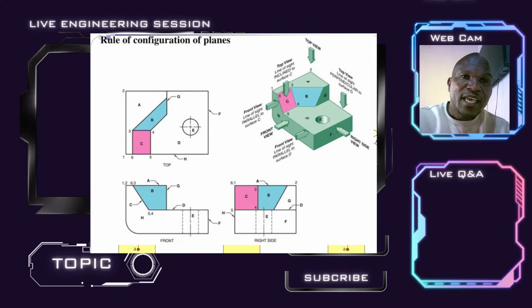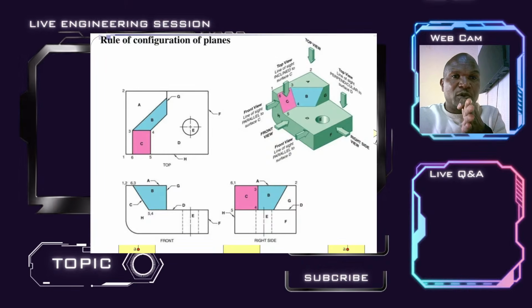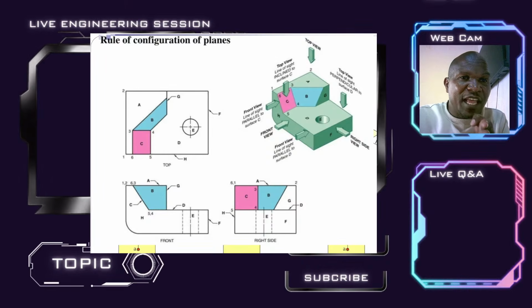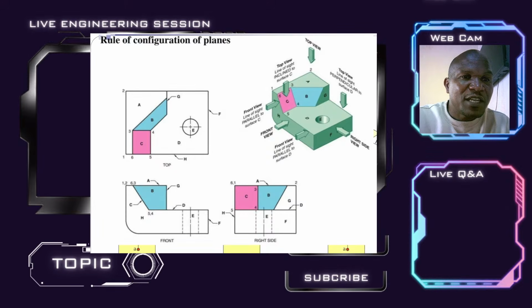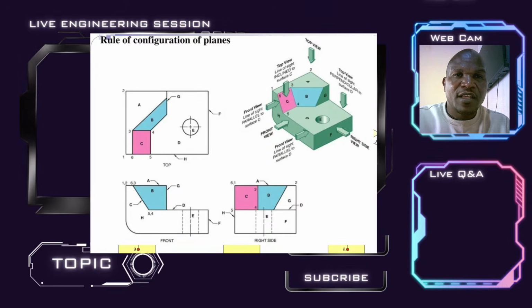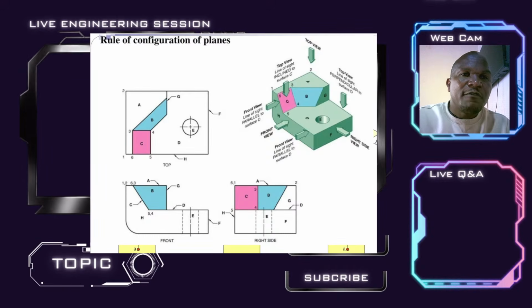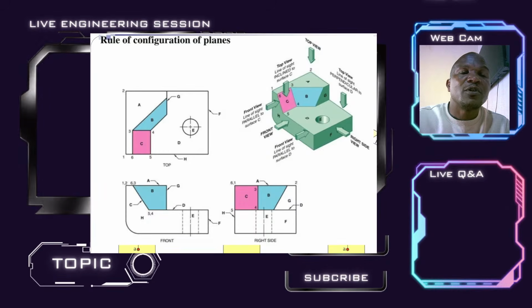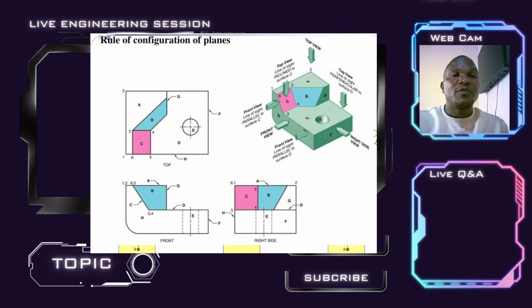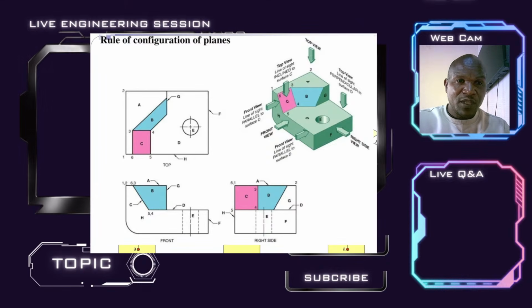Now 1, 2, 6, 3. Marking 6, 3 is a point which is coinciding, because when you're viewing it in front of you, you'll not be able to see 3, but you'll be able to see corner 6. The length 1, 6 is visible. It's the same as 2, 3 if it was viewed from behind. And also check 5, 4. 5 is in front of you, but 4 is tangential to 5 at a point when viewing from the front side.